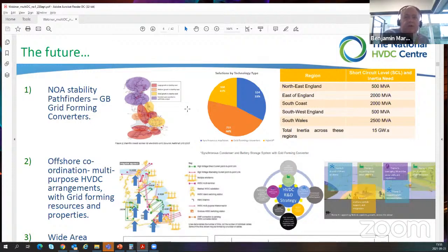So the grid forming solutions need to be robust to that, in particular robust to multiple events, to phase step movements, and to delivering solutions which, irrespective of the location of the fault on the system, are capable of holding the angle of the system. These are solutions which are seeking to provide time for more conventional forms of frequency response to activate. It's important to note that as you move towards lower inertias on your system, you do need to think about new paradigms for how you control frequency. It's not just about frequency measurement anymore.